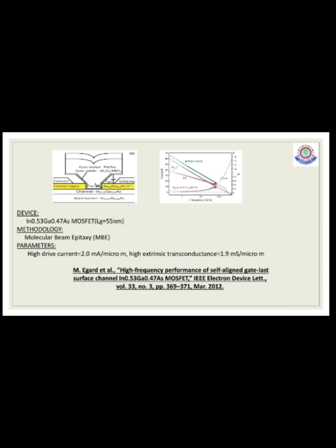The methodology used in this paper is molecular beam epitaxy. This process involves coating of a target material with a crystalline substance. This process has a huge setup with a large number of effusion cells and turbo pumps. Effusion cells will effuse molecular heat into the chamber. The turbo pumps will create pressure so that the chamber will be under vacuum condition. When the molecular film is effused, it will be bombarded and the target will be coated.